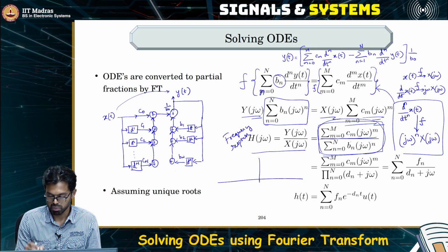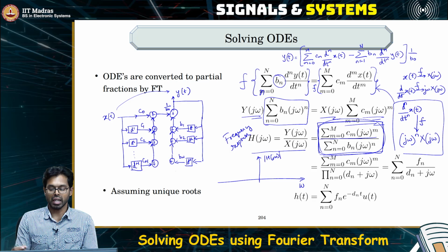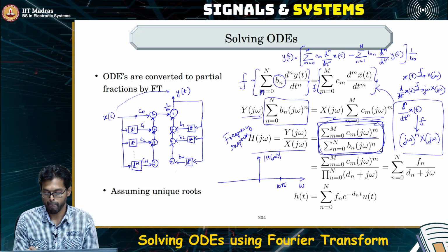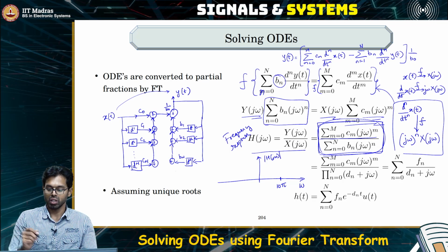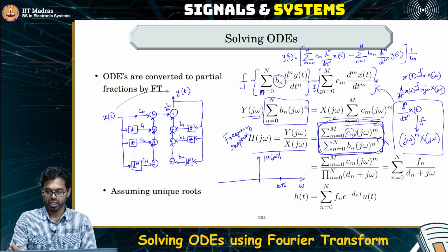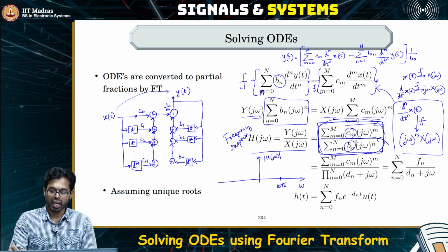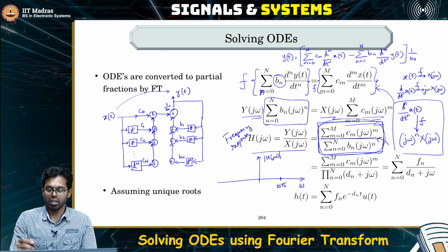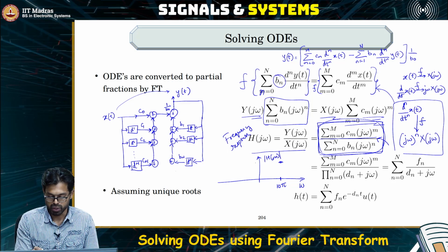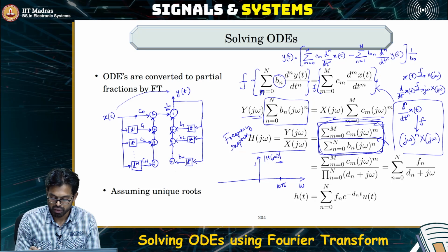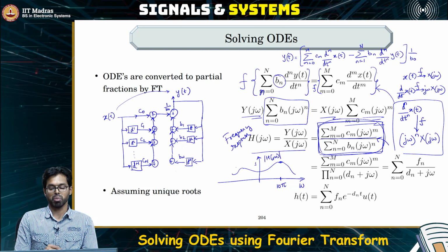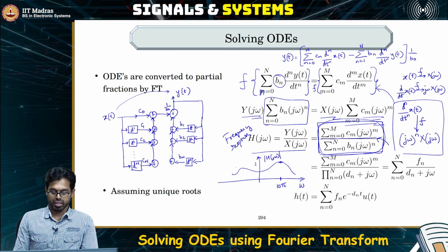Given that, let's say I want to know how the system reacts when I feed in a frequency of, let's say, 10 pi. I can substitute omega equal to 10 pi into this polynomial because I already know Cm and Bn. I can evaluate this and I'll know that at that particular value the amplitude is, let's say, 1. So I can evaluate this for all values of omega and find out the frequency response. This will completely characterize the system.